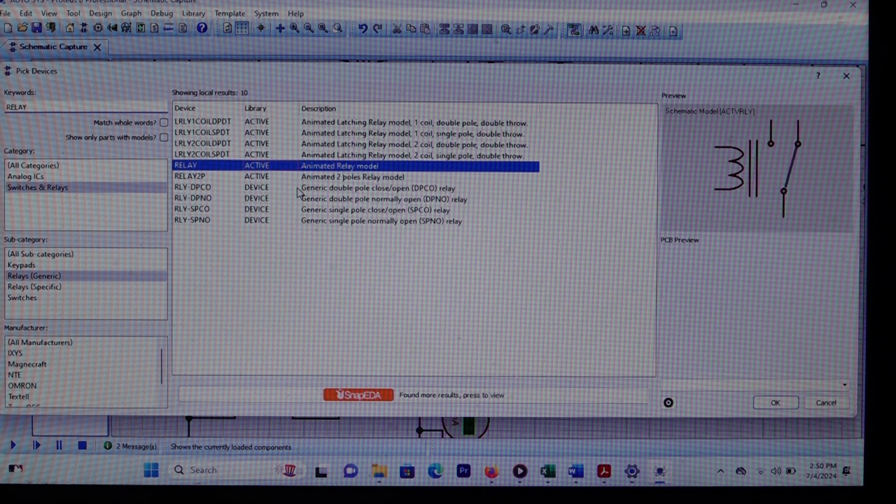But you can implement your simulation with a relay switch and its respective trigger voltage. So remember that the relay switch found in the libraries of Proteus has a trigger voltage of 12 volts, and that 12 volts is the default value.